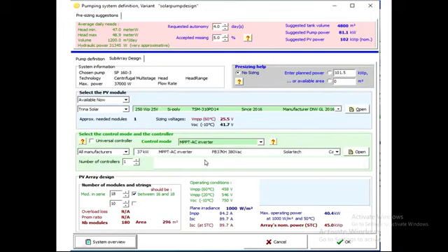When you enter this PV module and inverter, it will give the array configuration. You can check, we have got 180 modules. How much area is it requiring? 296 meter square. And this 180 into 250 will give the nominal power 45 kilowatt. This will be suitable for your design problem.